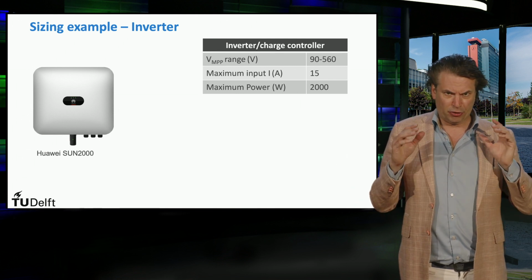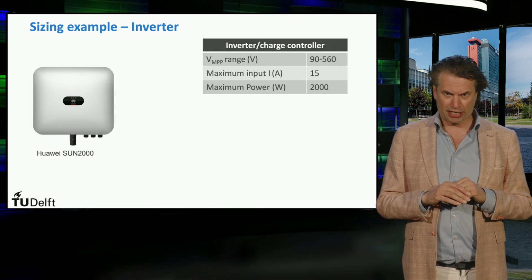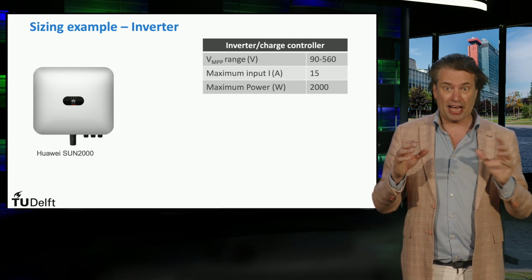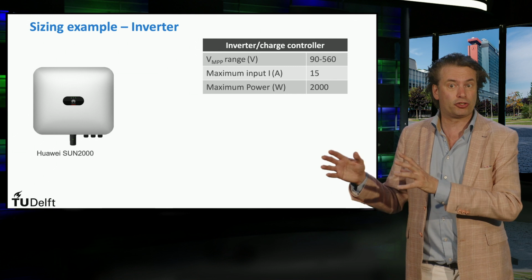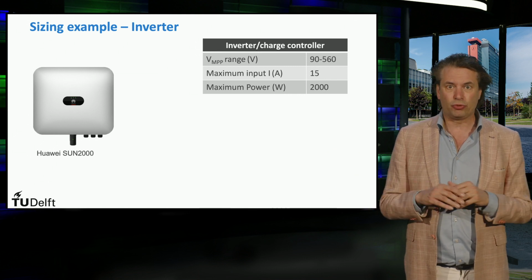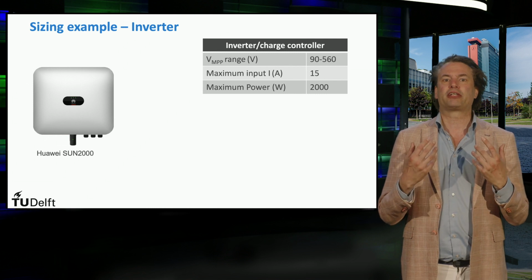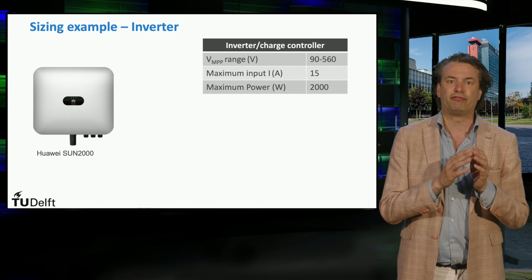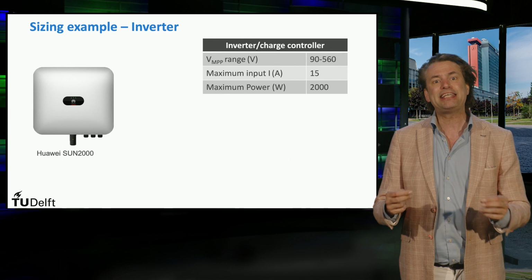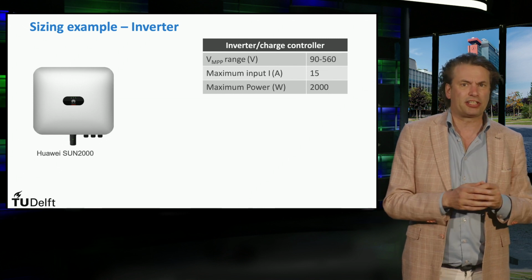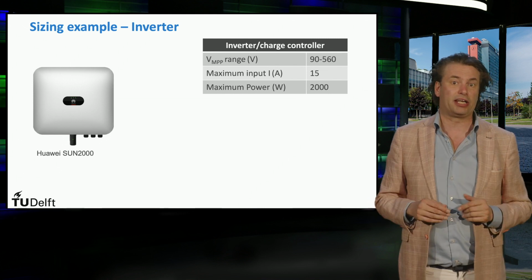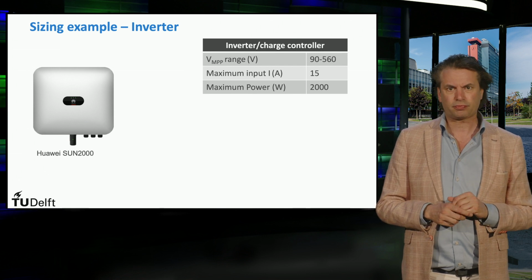This will not be true for a standalone system, as any surplus or deficit of power has to be met with a variation in the storage size, leading to considerable system costs. Consequently, in the grid-connected PV system, it's usually seen that the inverter is sized based on the PV array size and not the load size, like in the standalone systems.